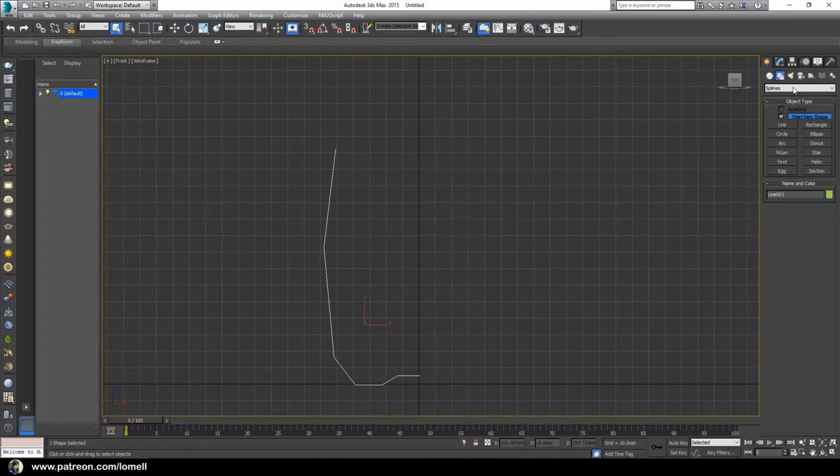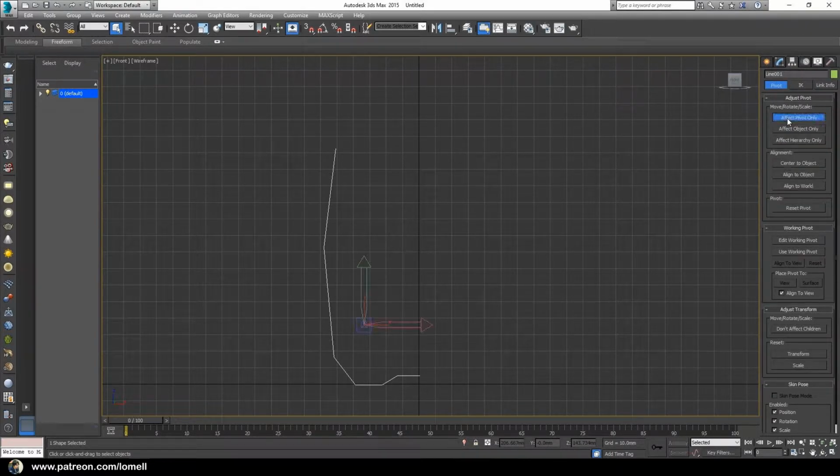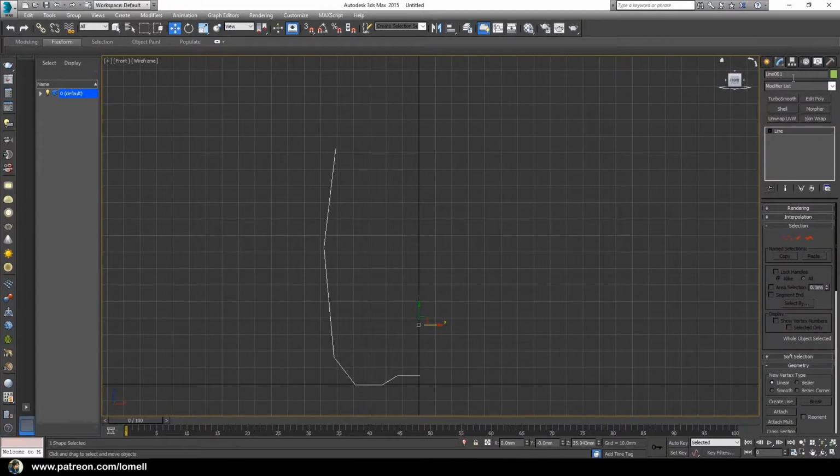Go to the Hierarchy tab and activate Affect Pivot Point. And we want to move its pivot point right at the center of this grid line using this Move tool. Drag over the x-axis, or under its transform type-in dialog in x-axis, just give it a value of 0. Okay, and turn off this one, and let's further edit its control points under the Modifier tab and expand this Line.